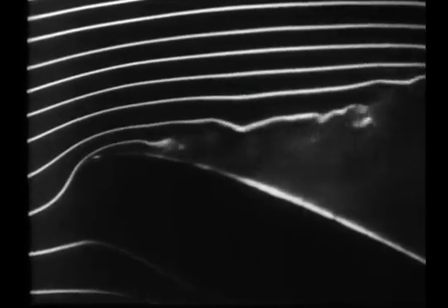We can watch reattachment in this slow motion scene. When the flow is separated, suction draws air into the slot from the entire separated region. Reattachment may be obtained either by the gradual extension of attached flow or by literally sucking away the separated area.